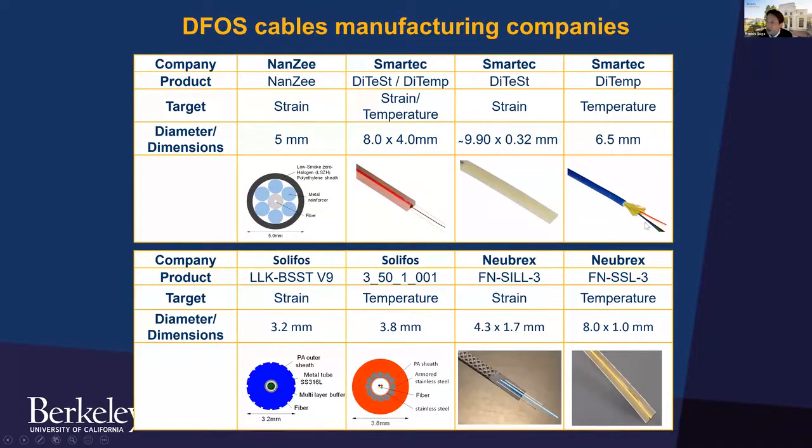You can now purchase a variety of fiber optic sensors, and they are made to be very robust. For example, you have a fiber which is very, very fragile, maybe less than 10 microns, but it's coated with a metal reinforcer or other material to protect it. The point is that when you step on it, that strain transfer goes through these layers into the fiber, and the strain outside is the same as the strain inside, and you convert that to light signals.